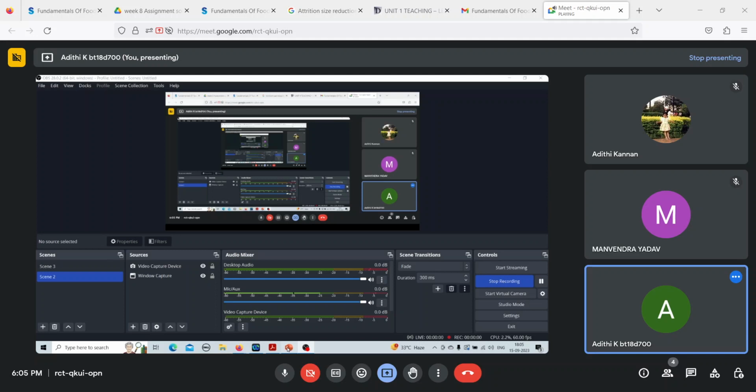So energy is equal to 2 into C into 1 by root of xp minus 1 by root of xf, where C is the constant that we saw in the previous equation, that dE by dx is equal to minus C x bar to the power minus m. So that is the C here. xp is the dimension of the product and xf is the dimension of the feed particle. So that is equal to energy here.